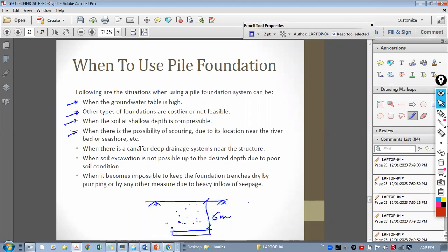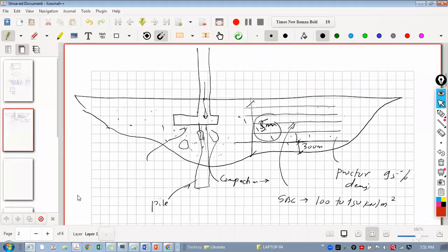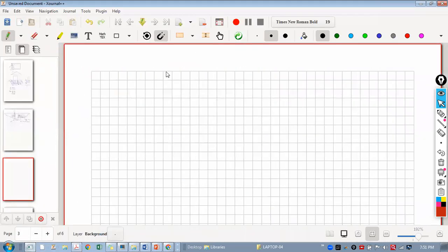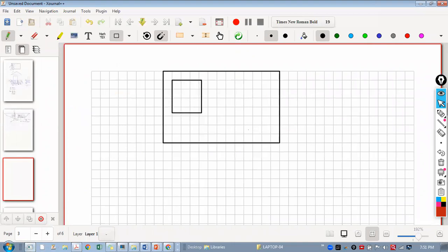And we can even think of pile foundation if there is an uplift issue. Sometimes for water tanks, generally, let me show here. Generally water tank levels are governed by the location or levels of the water tanks. So we cannot decide the level of the structure. It is decided by the architects or functional requirements.